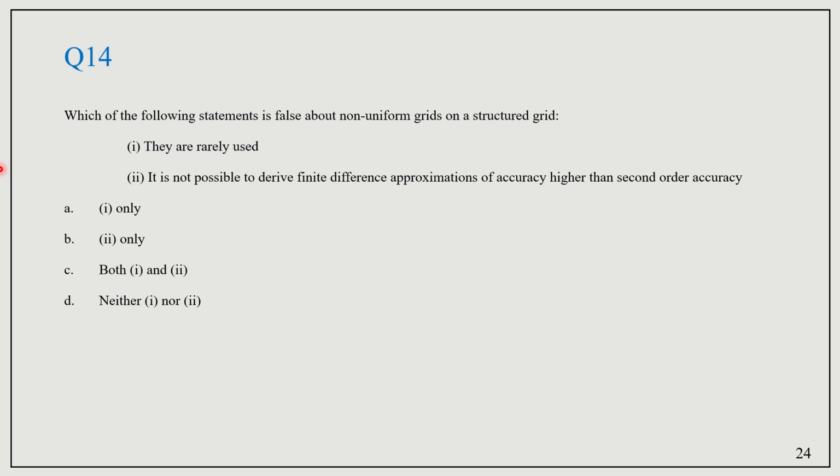The first statement mentions they are rarely used, that is, non-uniform grids in structured grids are rarely used. That statement is a false statement. It is not rarely used, rather it is used whenever required, based on the geometry and the conditions. So that statement is a false statement.